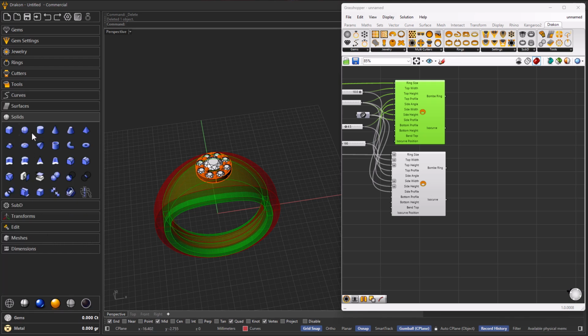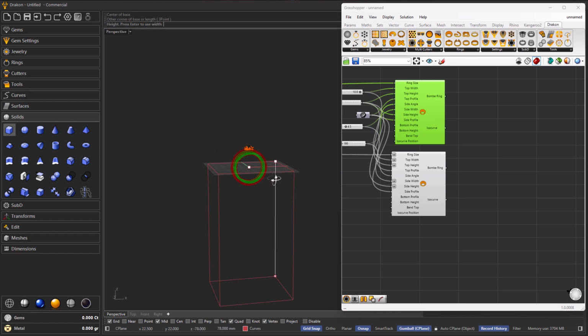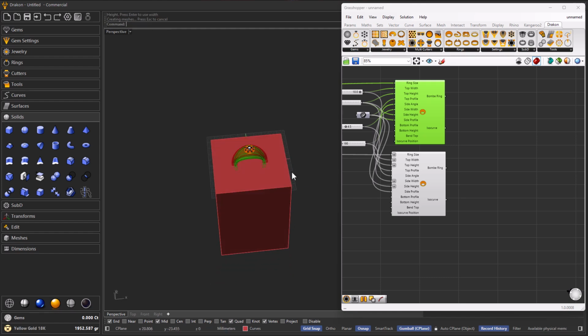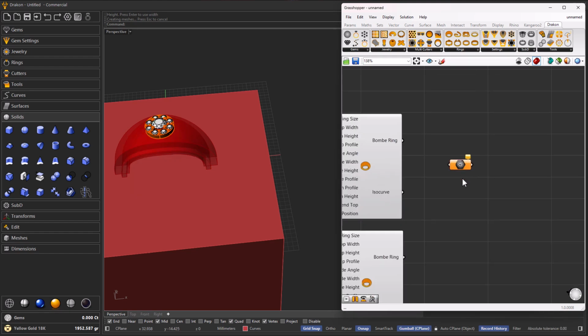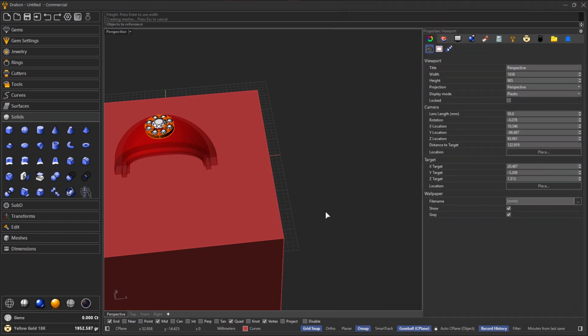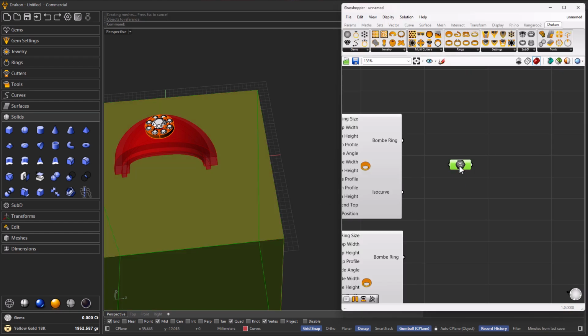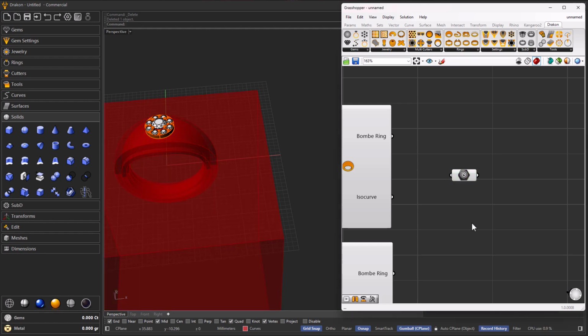So one thing I also want to use, and probably it's easier here just to create a box, is I want to make sure it's from the center. So I go to create a box, any size. Actually, it just matters to be on the C plane and goes down, because I'm going now to reference with the geometry. So double click geometry, right click, set one geometry, and I select the box. So this box will be my cutting object. I just internalize data so I can delete the Rhino box. And then now I use this one.